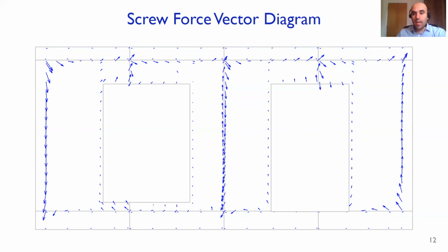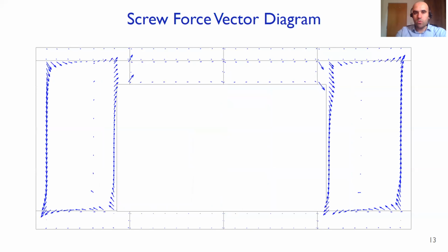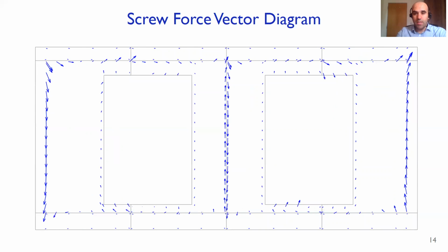As shown here, assessment of the shear force on screws at peak load capacity of the wall reveals that the screws at the vertical straight edges of the sheathing boards endure the largest forces, while the screws around the openings and in the top and bottom strips of the wall experience forces of lower amplitude. A similar trend was observed for walls with varying area, number, and position of the openings, as well as screw spacing.